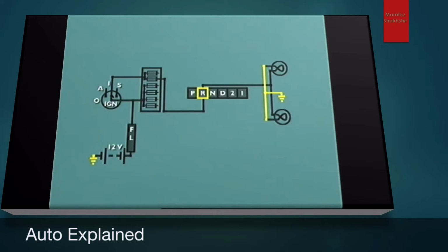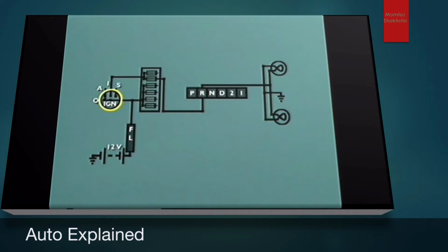through the vehicle frame. When the ignition switch is on and the vehicle is placed in reverse gear, current flows from the battery through the ignition switch to the closed reversing light switch on the transmission. Electrical current flows across the closed switch to the reversing lights and then returns to the battery by the earth return system.